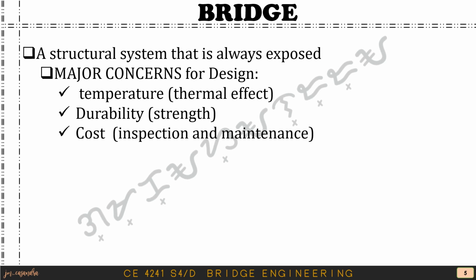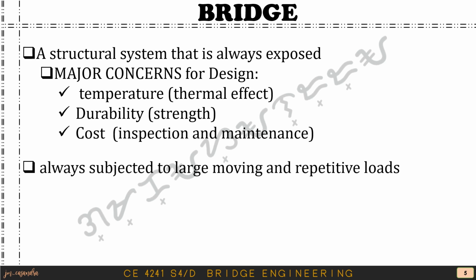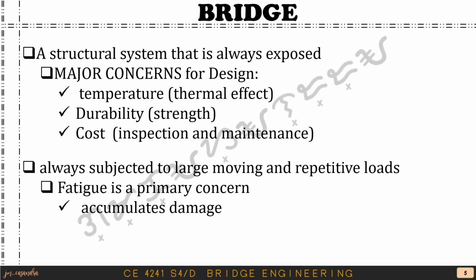It is a major concern since there will always be inspection and maintenance of the bridge, just like our highways or roadways. It will always be subjected to large moving and repetitive loads. Therefore, fatigue is also a primary concern in our design. So it accumulates damage over its design life or over its usage.